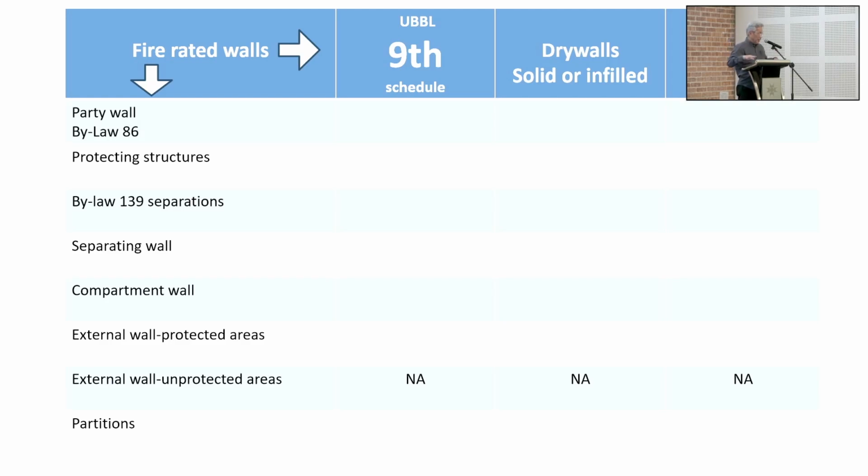as we stand today, in relation to what Bomba is expecting from us, I have to make this very, very clear. It's like legal speak already. In accordance to the directives of the Bilangan 2/2012, this is the application that Bomba will allow you to use drywall, solid or infill, or conventional drywalls, not classified as solid or infill. And of course, UBBL 9 schedule. All prescriptions in UBBL 9 schedule, you may use it for all of these elements.